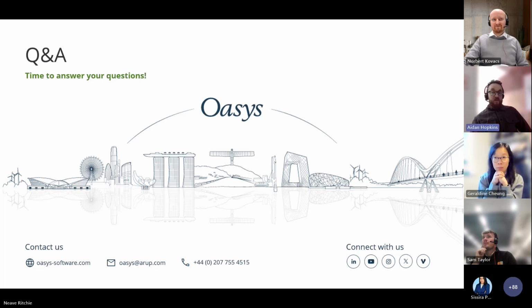I'm happy to jump on this very quickly, from a tunneling perspective. Go for it. Depends what curve you use, and XDisp does have the guidance there for doing subsurface displacement. So you will not be getting the same result at depth. If you tick subsurface displacement, you can pick up the curve at depth.